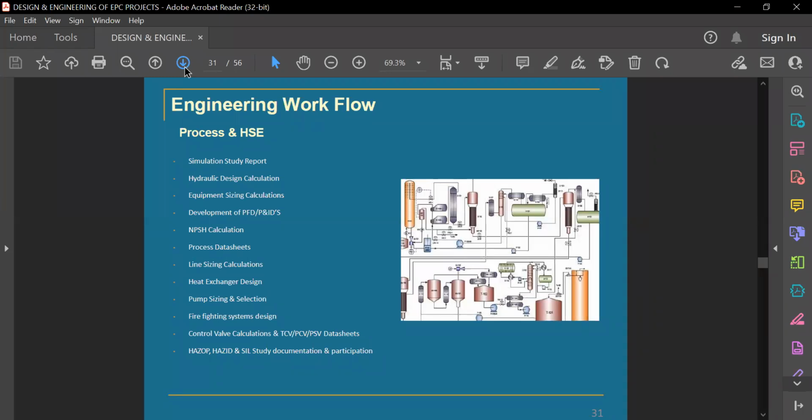But safety integrity level, again the second study, which is a major second study. So here, for safety integrity level, if any transmitter fails, then is another transmitter there or not, and then the probability of failure on demand, or availability of the transmitter, is ensured. If it is not there, then we have to put in another transmitter. So one out of three, two out of three, and all those voting arrangements.